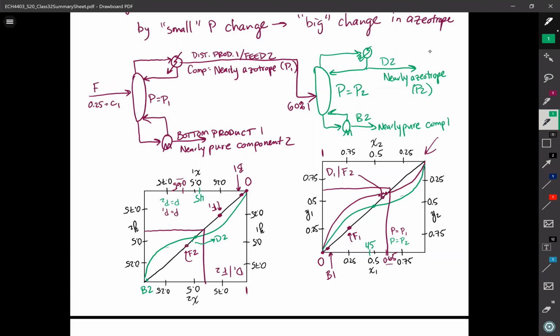So again, just to recap, there's nothing special to pressure swing distillation. It's just 2 distillation columns. The specifications get a little bit funky because of the azeotrope. And then the only other weird thing is that one of the designs will be upside down. Unless you have really good spatial skills, you could always use the same diagram, but make your rectifying section operating line kind of like this and step stages like that if you want. So you could do the whole problem upside down if you wanted to. I typically prefer to just rotate my entire paper such that it's similar to what I know.